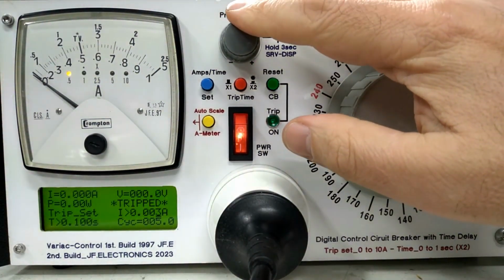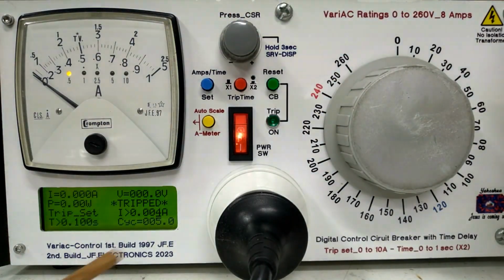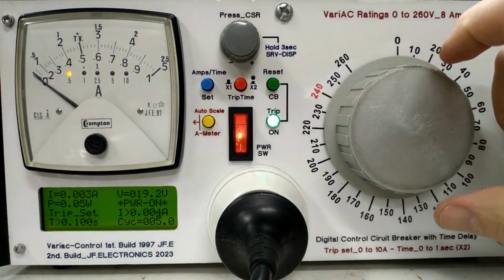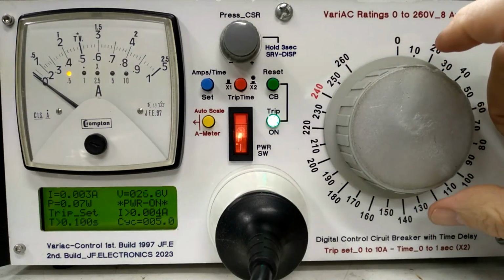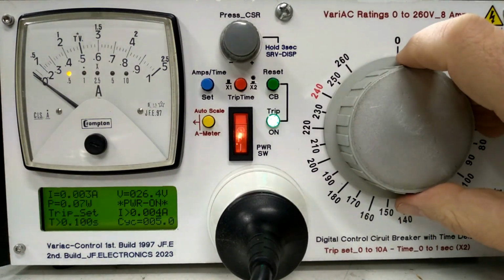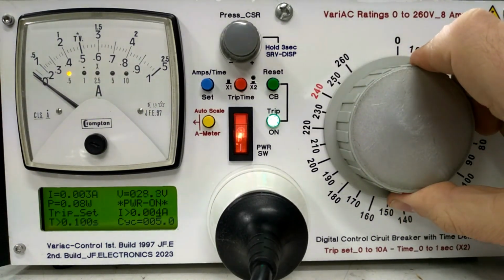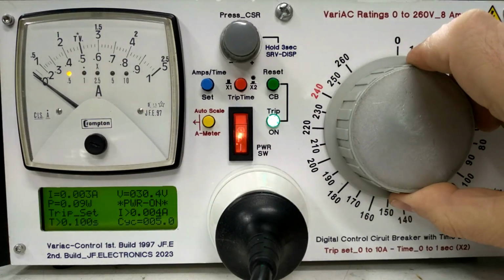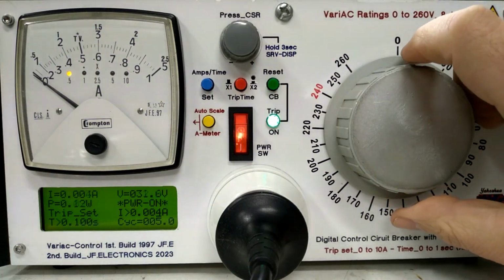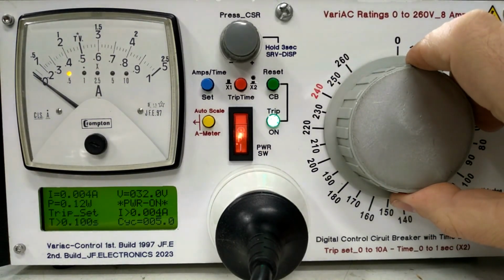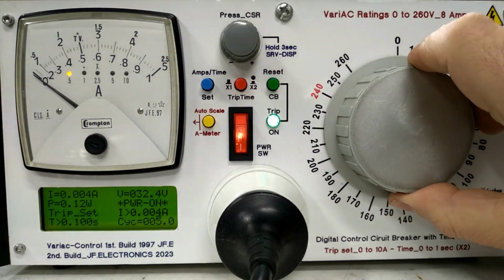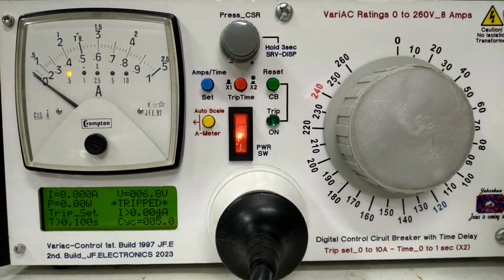Let's do a 4 milliamp test. So I've set the current settings for 4. Reset it, drawing the 3. That's what it tripped last time. That's what it's still reading, the current draw of the load. 28, 29 volts, 30 volts, 31.6, 32. It's flickering to 4. We go a bit more. Tripped at 4 milliamps. Pretty good.